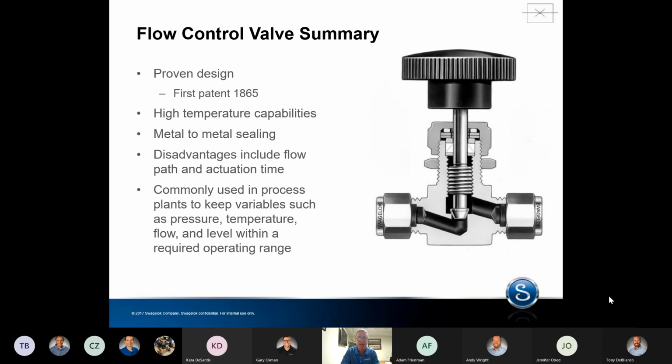A quarter turn ball valve should not be used. The reason being that because of the quick opening, any particulates in a line upstream of the valve will be carried downstream at a high velocity when the valve opens. When those particles strike a surface in the system, the impact energy is released as heat, and these small particles can become hot enough to ignite larger materials in the system. So a needle valve, which opens slowly, reduces the downstream velocity and the risk of ignition.